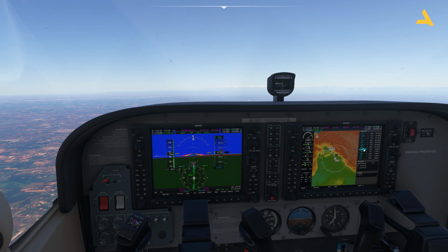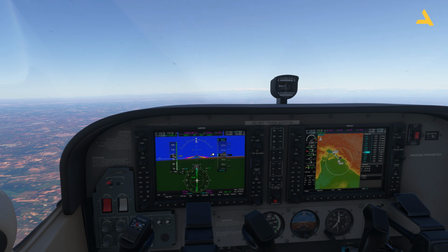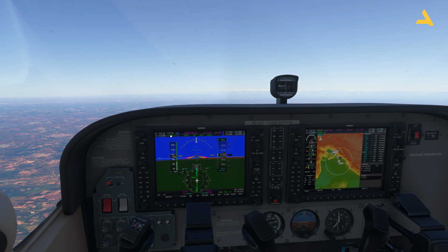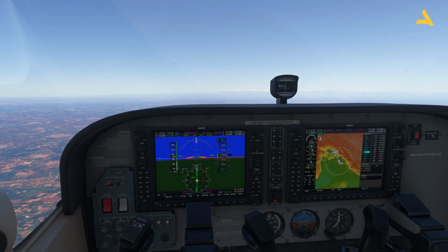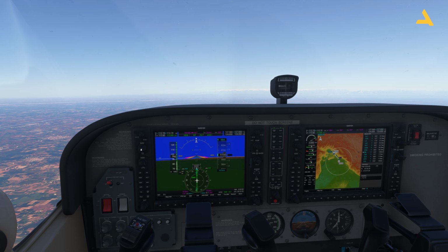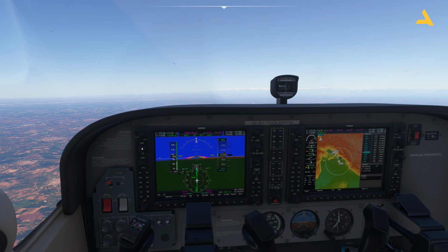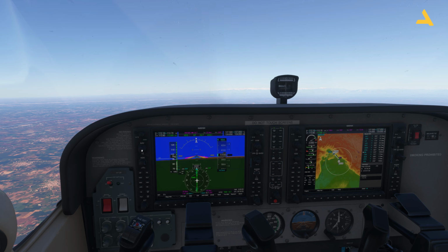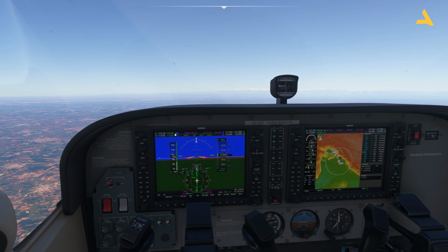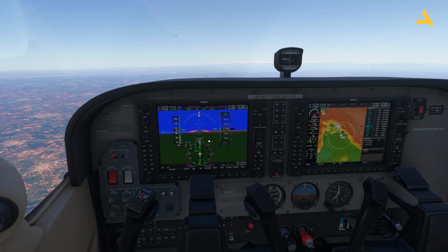Now after Sialkot, I will be tracking this. Now interestingly, as I'm no longer tracking the LA, I can just keep the frequency of RN in a standby frequency mode. So let's change it from nav2 to nav1, and just tune into this frequency 112.10, and just press the swap. Now 112.10 is the active frequency, and you can see its identifier is coming RN.